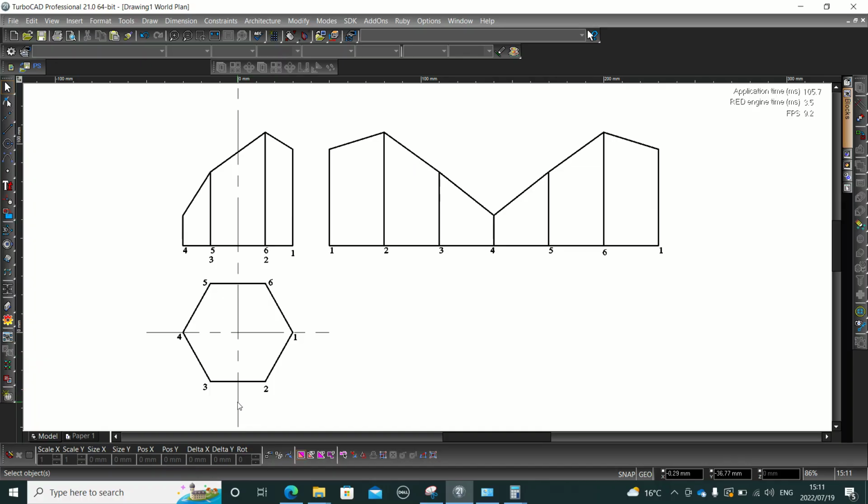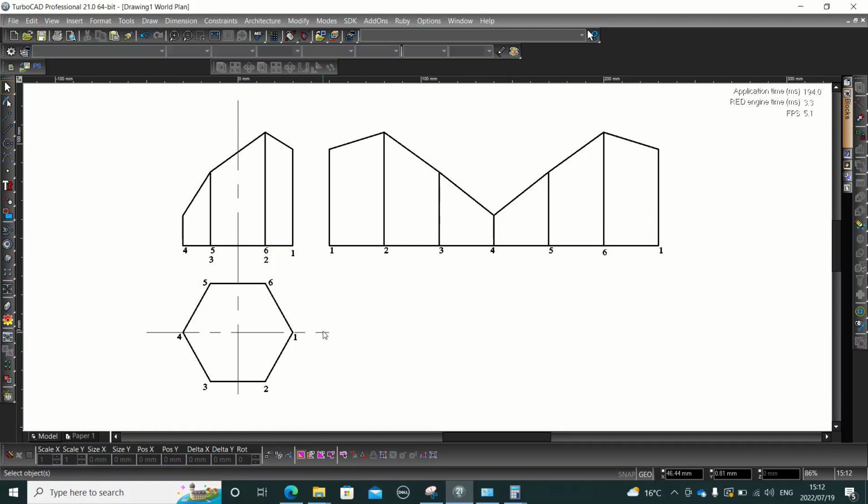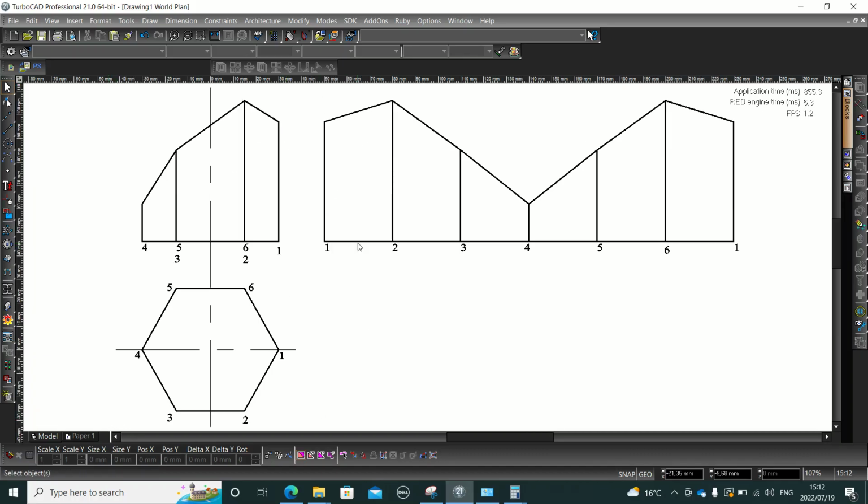The center line is long. Let me click on it and shorten it. Let me deactivate the snap mode. Click on it and drag to shorten. Even this one is a little bit longer. So I'm tidying up my drawing. Once I'm done, I reactivate my snap mode. I can realign my drawing. Now I need to transfer this. I'm satisfied now, my drawing is complete.